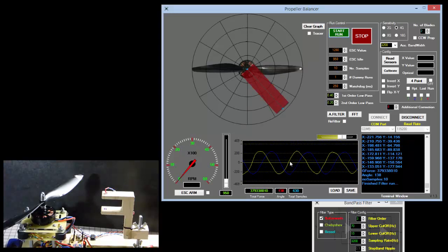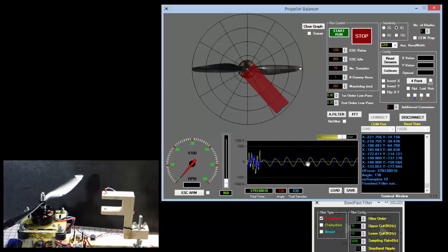So what happened, and we can see some major differences here, including if we zoom out. Now you can see the functionality of the graph, that here's the raw signal coming out of the accelerometer, and after DSP was applied, here's what comes out. So it should be completely apparent that the way this bandpass filter is working is absolutely spot on, right, in terms of isolating that imbalance.